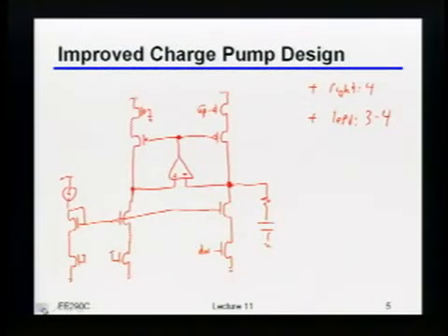Oh, yeah. A question on the previous slide. Sure. Is there any constraint on the bandwidth of the op-amp? Okay, it's a good question. It depends on how precise you want to be. To zero order, you don't have to have super high bandwidth here, only because you know that the control voltage is moving very slowly, relatively speaking.